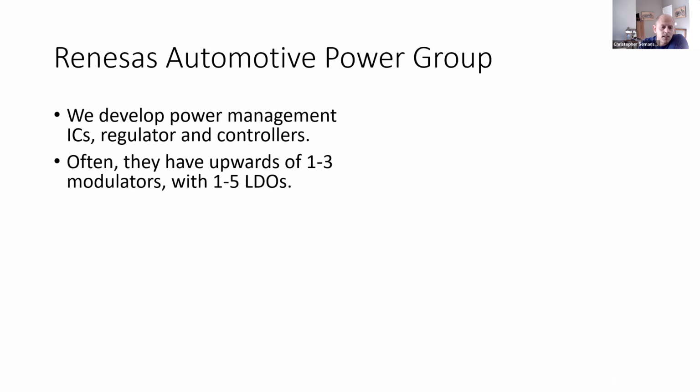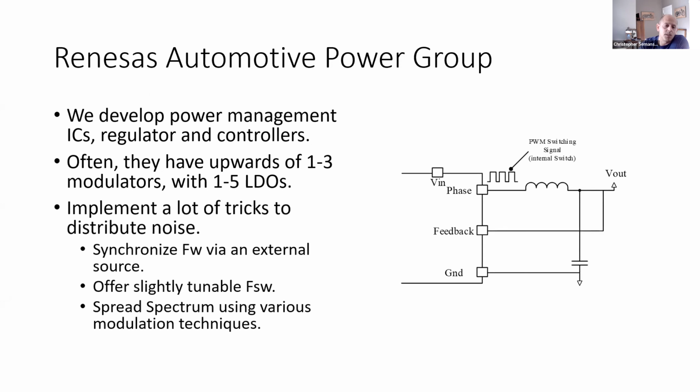So our PMIC that we make, if some of you are aware of it, we have upwards of 1 to 3 modulators and 1 to 5 LDOs. So it's a really handy little piece of equipment to have, but it's also a very noisy little piece of equipment to have. So we implement a lot of tricks to distribute noise.